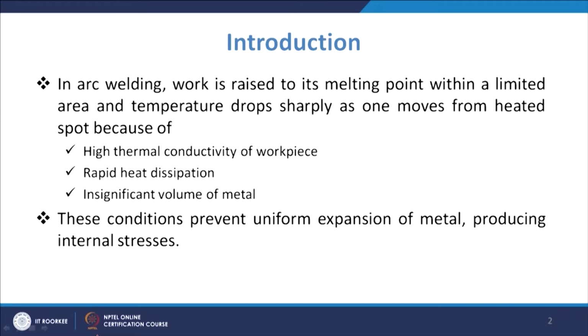If you talk about casting, you have a large volume of metal, whereas in this case you have a very small metal pool which is getting cooled. So that volume is also smaller, you have rapid heat dissipation, and the heat conductivity on the sides is higher.